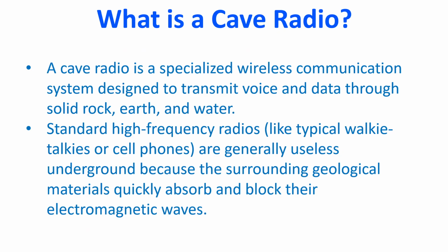A cave radio is a specialized wireless communication system designed to transmit voice and data through solid rock, earth, and water. Standard high frequency radios, like typical walkie talkies or cell phones, are generally useless underground because the surrounding geological materials quickly absorb and block their electromagnetic waves.